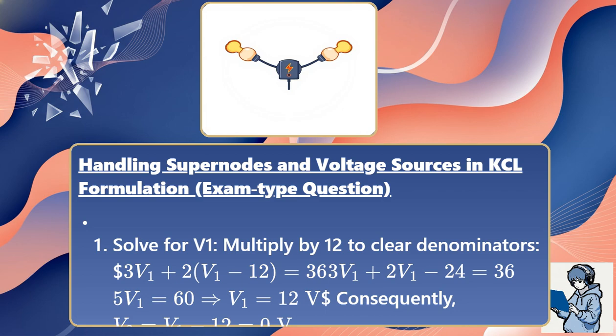Multiply by 12 to clear denominators. 3V1 plus 2(V1 minus 12) equals 36. That expands to 3V1 plus 2V1 minus 24 equals 36. Combine terms: 5V1 equals 60, therefore V1 equals 12 volts. Consequently, V2 equals V1 minus 12, which is 0 volts.